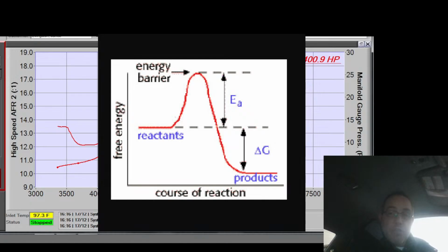For ethanol, because there's so much material being put in the cylinder, and it's got a big cooling effect, the higher, hotter plug helps to do one thing I forgot to mention earlier, is it helps to create localized atomization of the air-fuel charge. It's not setting it off, but the stuff that hits the plug and gets around the plug is more likely to vaporize and be more homogenized and be at a higher energy state just from the heat of the plug before the ignition event happens.